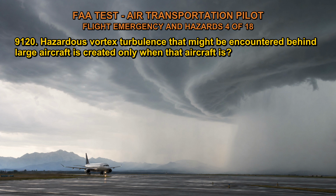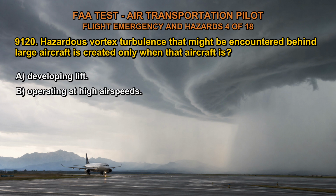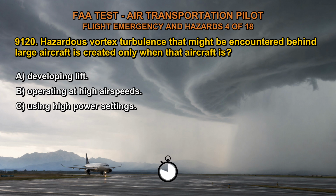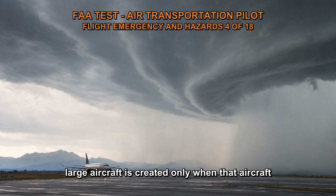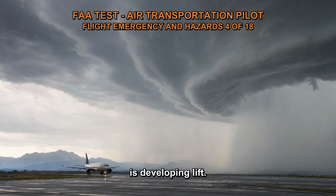9120. Hazardous vortex turbulence that might be encountered behind large aircraft is created only when that aircraft is A. Developing lift. B. Operating at high air speeds. C. Using high power settings. The correct answer is A. Hazardous vortex turbulence that might be encountered behind large aircraft is created only when that aircraft is developing lift.